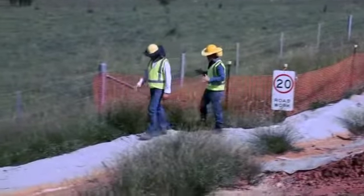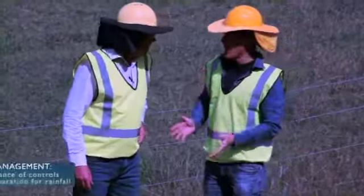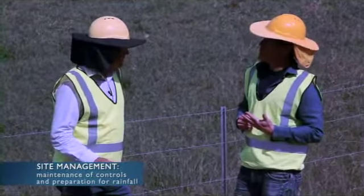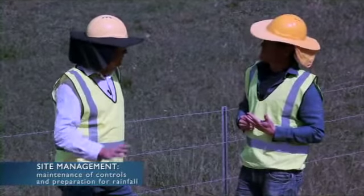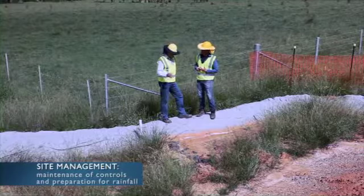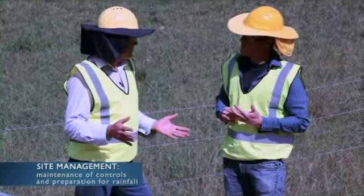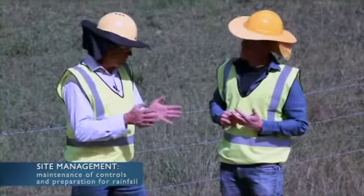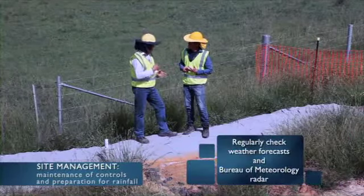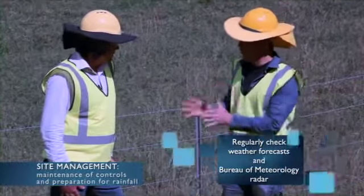Now, Chris, we've been monitoring all of these control points to make sure we stay on top of site conditions, but I imagine maintaining the control points is important. Absolutely, Pete. So our controls can get damaged over time, particularly with high rainfall events or high velocity flows running through the site. And over time, a lot of the controls will actually fill with sediment. But it's not just the controls filling with sediment that might have an impact. Damaged controls can actually make the situation worse. So if we've got high flow rainfall or runoff running through a hole in a control or a gap in a control, it can actually create erosion itself and continually scour the site. Yeah, sounds pretty ugly. So it's important to stay on top of those maintenance issues of those control points.